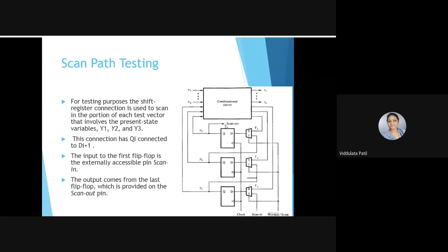Okay, and then you are going to get the Y3 output. Now here we have applied a sequence or pattern, that is 0 1 0 1 1 1, sorry, 1 0 0 1. Okay, so the earlier pattern that I said. So we applied it, and what is going to happen at the first clock rising edge, this 0 will be shifted. As this will work as a shift register, after 8 clocks we will get the pattern 0 1 0 1 1 0 0 1 here.